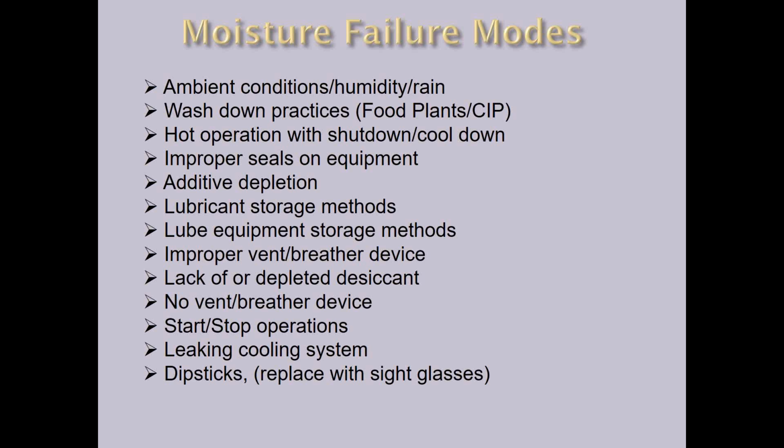So I've got lack of or depleted desiccant breathers. I've been in many plants where the breather's been on there so long that it's turned dark or it's changed color and nobody's changed it. I was at a plant in Nebraska about 2 years ago. The breathers have been on there so long they had mold growing on the inside of the breather. So again, we have to change those breathers out to keep that moisture out.